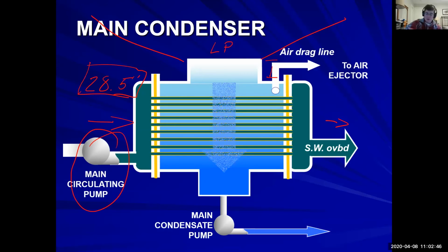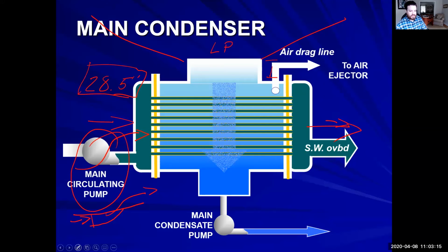Ship has a scoop we can use. Yep. So it literally is a scoop. It's at the bottom of the hull. And it literally is just a scoop where we're using the ship's momentum to pick up salt water and push it through the system. It comes through this section and it just gets dumped overboard. It's not mechanical in any way. We have a valve and that's about it. Just know that there is a scoop.